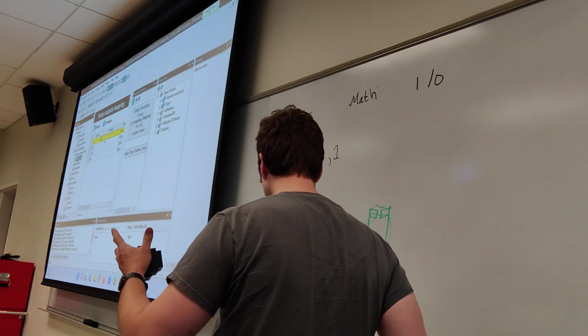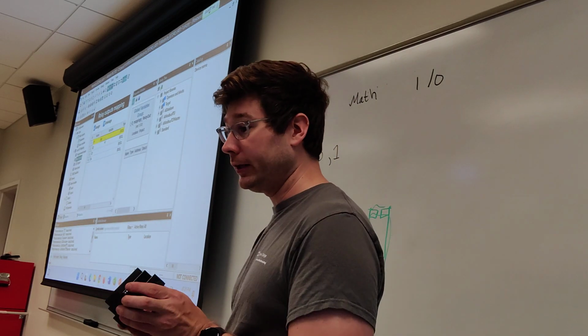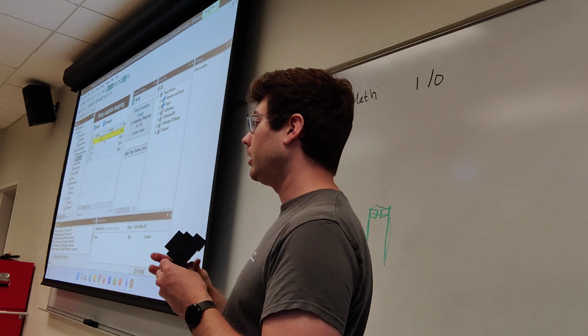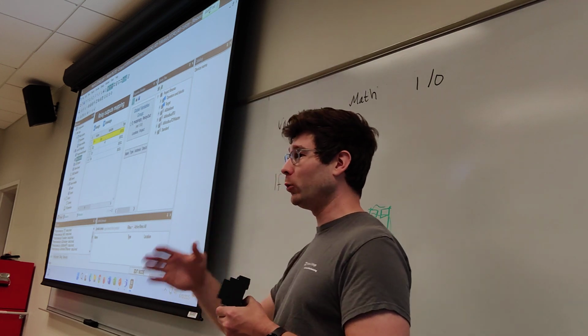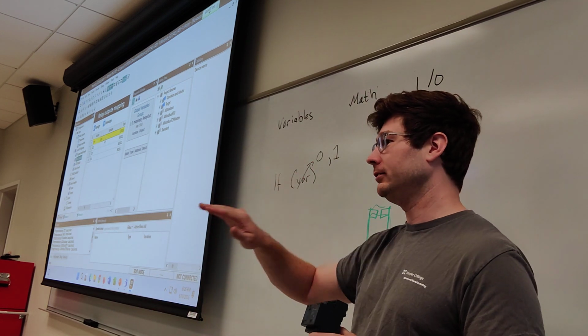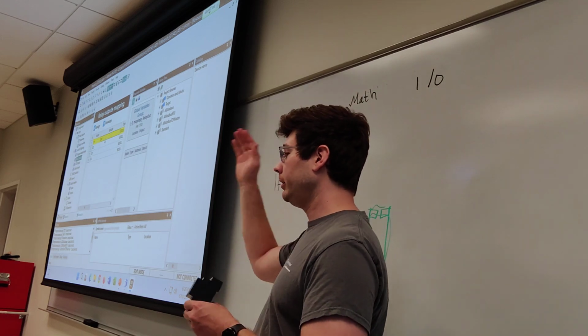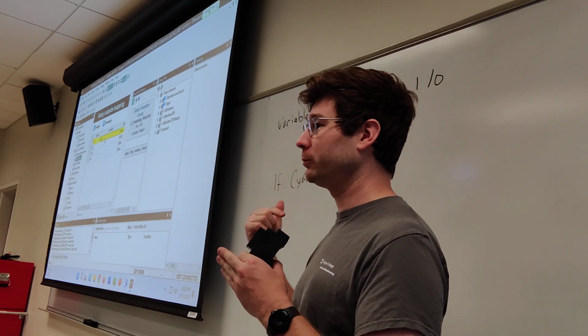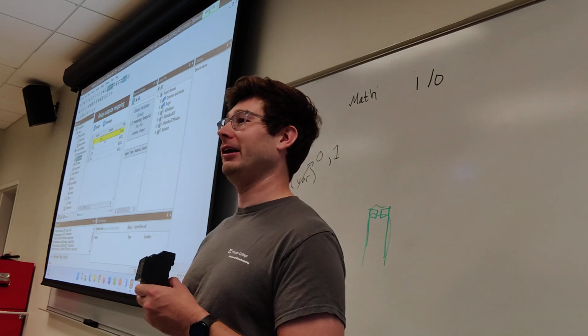All right, but we have a fan on our first relay, and now, just like our inputs, when I say fan equals 1, literally in the code, one line that says fan equals 1, it will turn on our relay, it will close those contacts, which will expose the fan to 120 volts and turn it on.